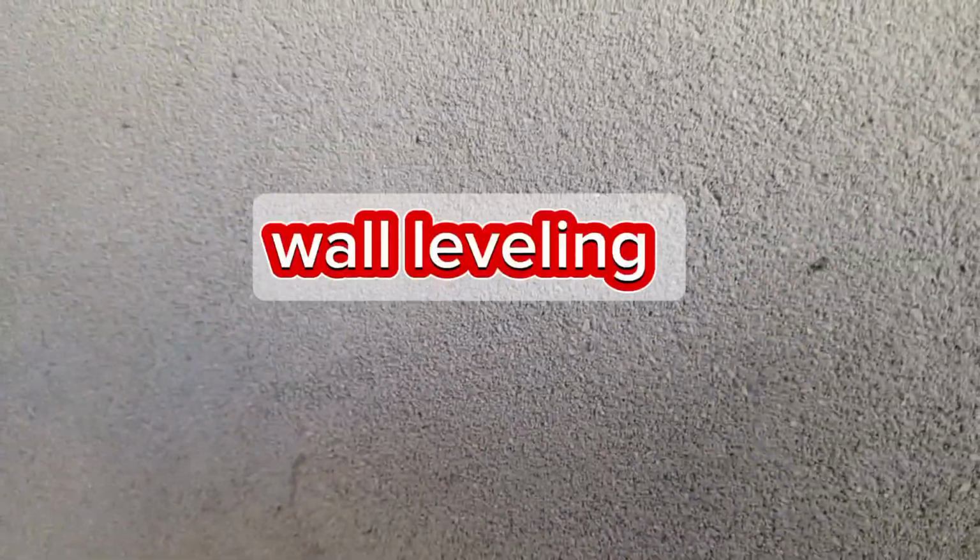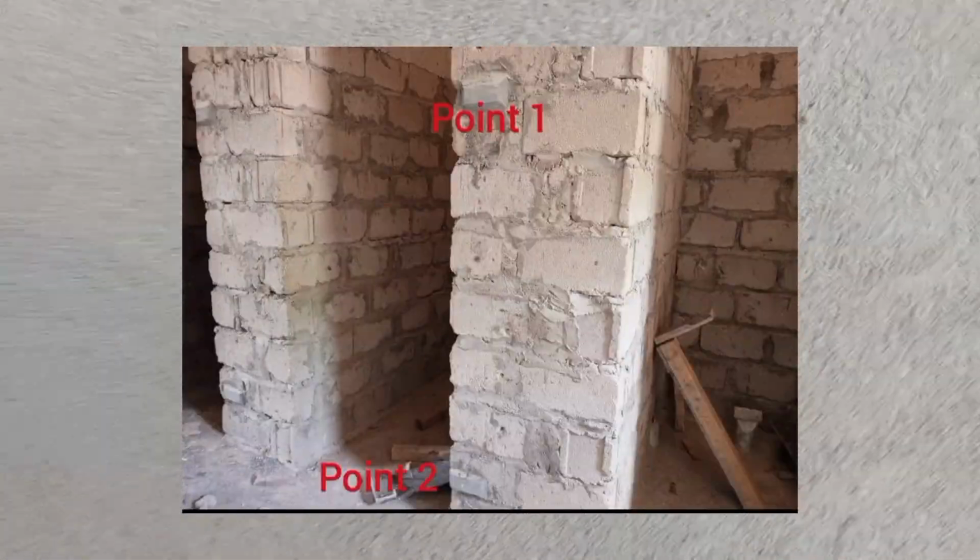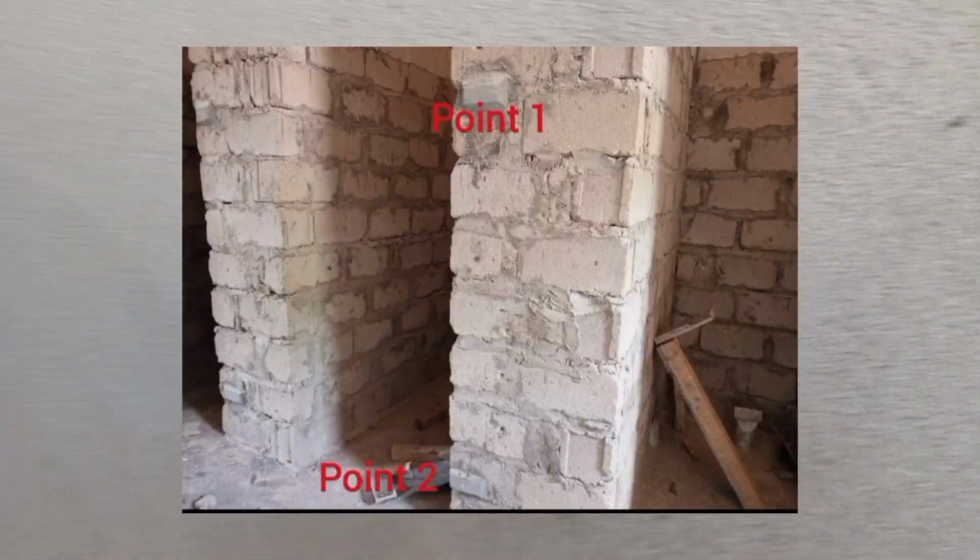So how do you do wall leveling in layman's language? For wall leveling, you can do points. You can introduce points using the cement sand mortar, on the wall. You can do 3 points on the wall: one point at the top, another point at the middle, and the last point at the bottom.